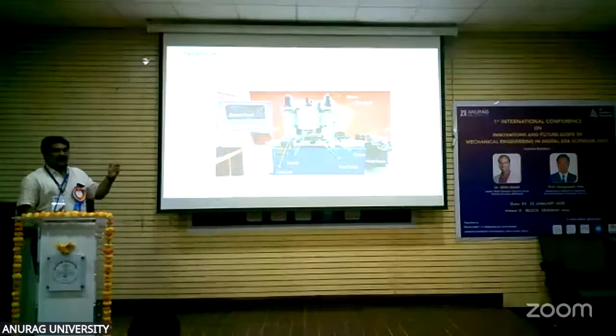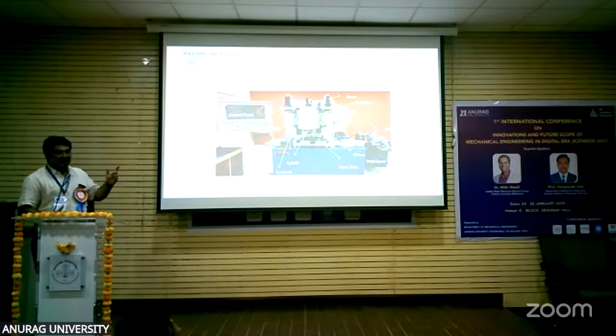Based on previous scholars' references, the minimum we are taking is 900 RPM, and we could go to higher speeds also. But then the material will scatter from the weld joint. With more heat, the metal joining is weak. That's why we go for medium temperatures for the weld joints.